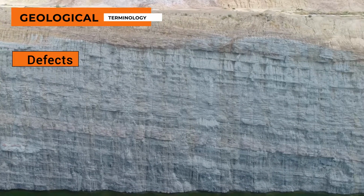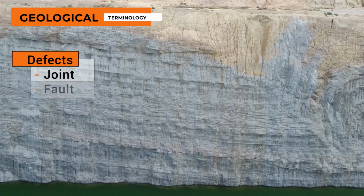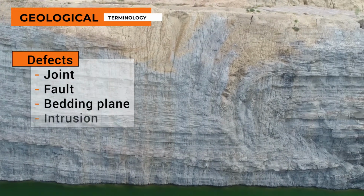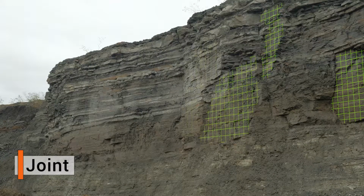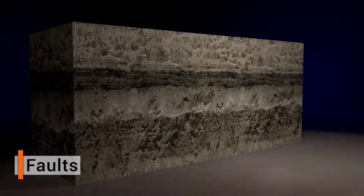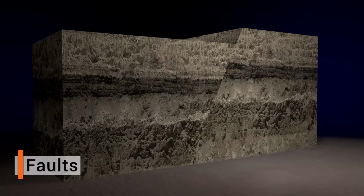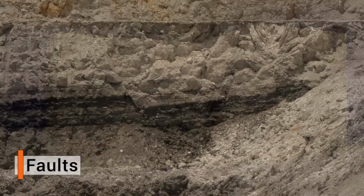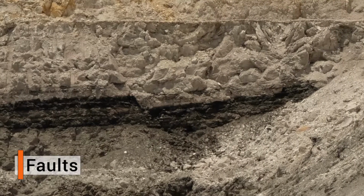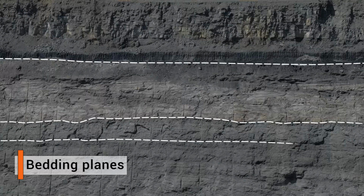Defects. This is an overarching term used to describe any break or fracture in the rock, such as a joint, fault, bedding plane, or intrusion. Joints are fractures in the rock along which there has been little or no movement. Faults are fractures along which adjacent blocks of rock have moved either vertically and/or horizontally. The zone around the fault may be further weakened by soft clay material referred to as fault gouge. Bedding planes are contact surfaces which separate different rock types.